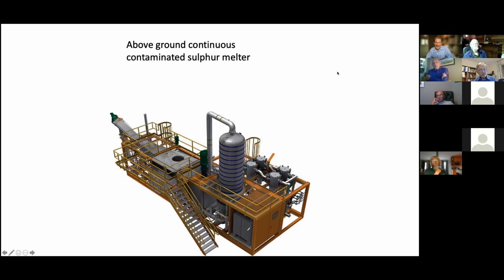So typically we design this for a throughput of something like 35 to 40 tons an hour, pumping out to the settling tanks, or to these filters first. These are the 4 filters that we use, wedge wire filters. We'd circulate at 450 tons an hour back into this unit.